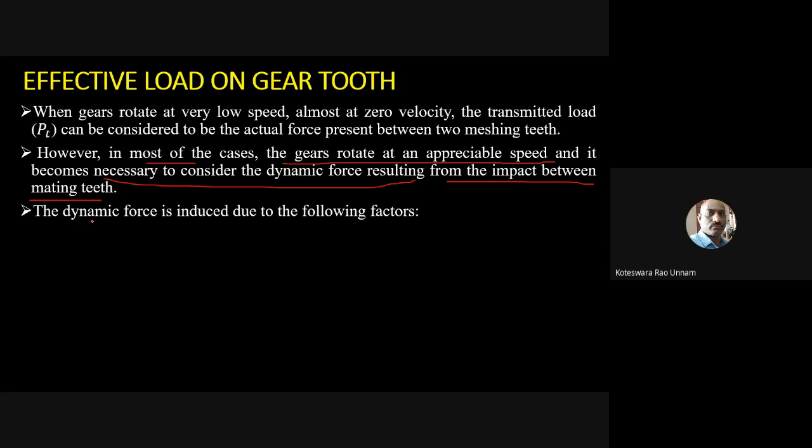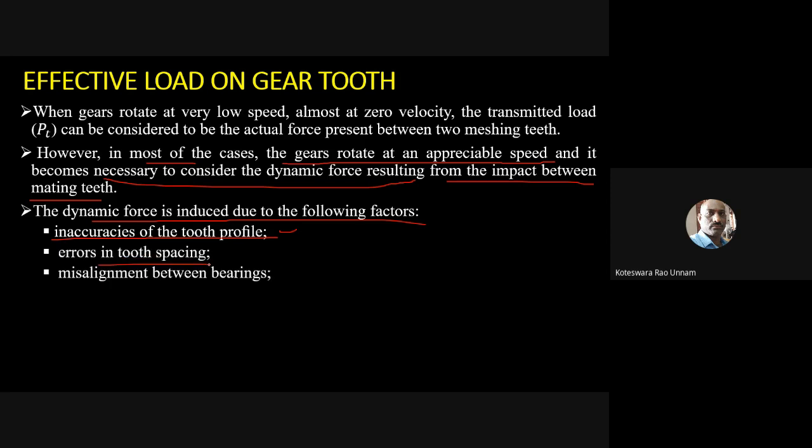So the dynamic force is induced due to the following factors. Why do you need to apply this correction factor for this load, in order to account for high speeds? The reasons may be inaccuracies of the tooth profile, that means your involute tooth profile is not properly cut, errors in tooth spacing, misalignment between the bearings, and elasticity of the parts. And finally, an important thing is inertia of the rotating parts. So due to these things, you need to consider the dynamic load.